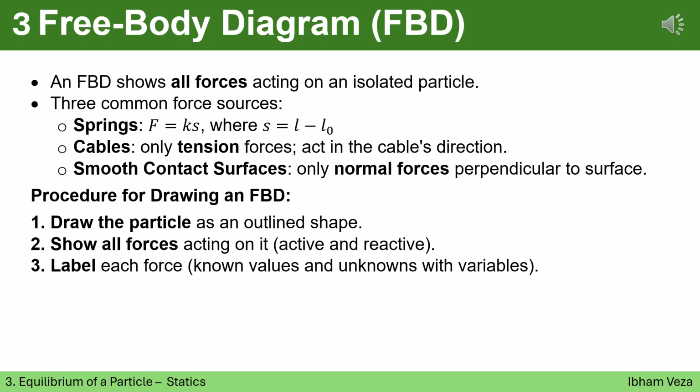Springs generate forces according to Hooke's law. Cables carry tension only, and smooth surfaces provide normal forces perpendicular to the surface. When drawing an FBD, always isolate the particle, show every external force clearly, and label known and unknown quantities. A correct FBD is often the key to solving the entire problem correctly.